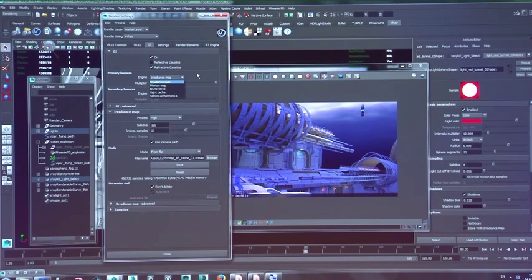I'm not going to have the time to explain exactly why, but you can come by later on and I'm going to explain. Now, the cool part about the irradiance map is that it allows me to cache the GI so that I can render it first and then reuse it for each of my subsequent renders, which is a great help for me when adjusting the shaders and adjusting the final rendering. Also for the final rendering, of course.